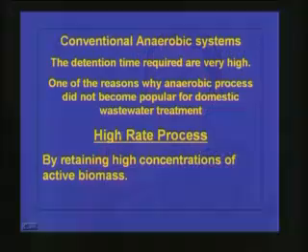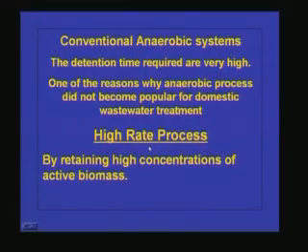So, if you allow the biomass generated in the system to go out, what will happen? The system will not have enough biomass, so naturally the treatment efficiency will come down. If we can clearly divide the hydraulic retention time and biological sludge retention time, then the system can hold a lot of biomass inside. Once the biomass concentration inside the system is very high, naturally the treatment efficiency will be high, because in any biological system, as I have already told many times, the workers are microorganisms. If you can increase the number of workers, definitely the treatment efficiency will be more. That is the very principle of high rate processes.